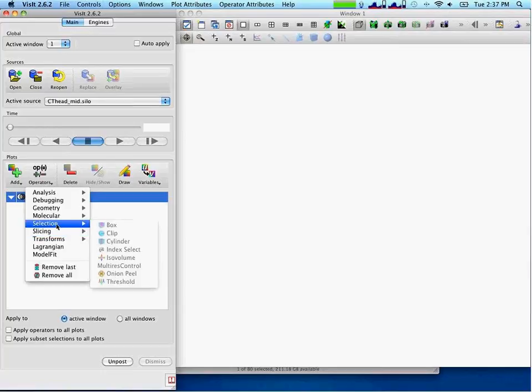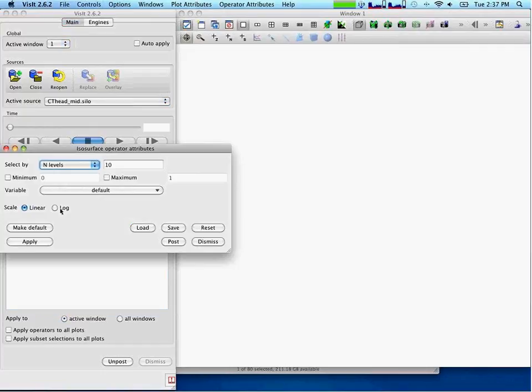Another popular one to use is called isosurface. The underlying compute model is that it goes through all the data, you give it a particular data value, and it finds all the places with that value, and in a sense builds a mesh according to it. So let's pick a value of, say, 2 on the data.